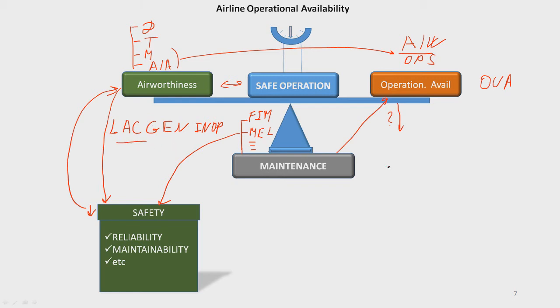Based on my experience, for commercial aircraft, it takes 3-4 hours. Replacement takes a little bit less, but when you replace it, you need to test the system, and for this AC generator, to test the system, you actually need to run the engine. So that's what takes 3-4 hours. So maintenance goes back and takes 3-4 hours.